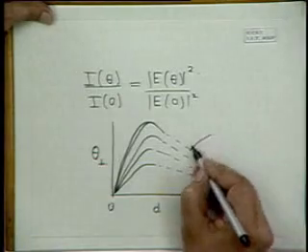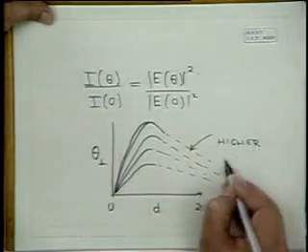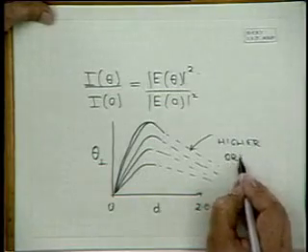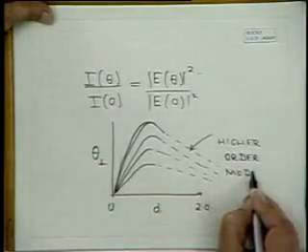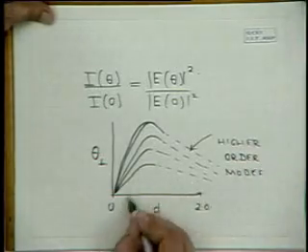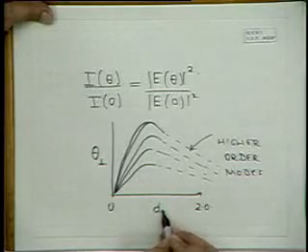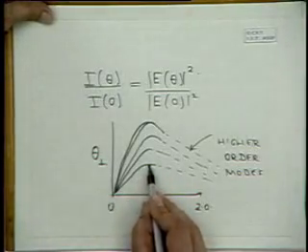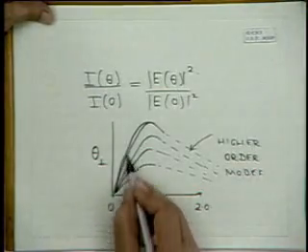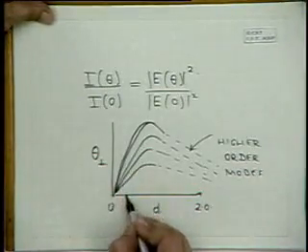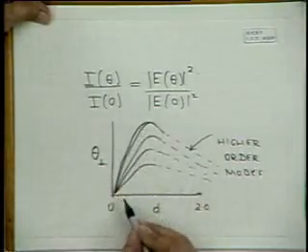The dotted lines are where, if you have higher values of D, you have the possibility of higher order modes. We do not want a high value of theta. We want a low value of theta, so we should stay somewhere here, for low values of D. You get low values of theta. So we do not want this maximum.